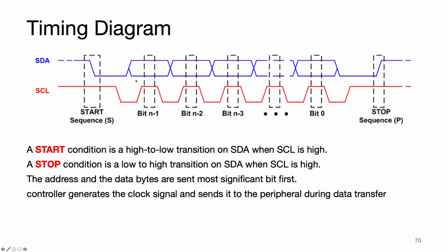Normally, we're used to seeing the clock rise here and fall here, with the data transitions right in the middle. This is a level-sensitive transition inside here. It has to be on the rising edge, or on the flat part here. This is where the data is clocked in. So it's a somewhat unique physical layer. We call it the PHY layer, because this is what the actual signals, as you'd see on the oscilloscope, are doing.